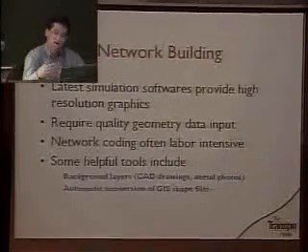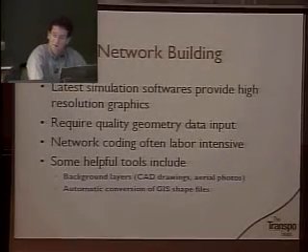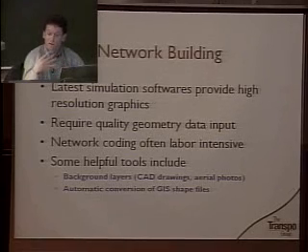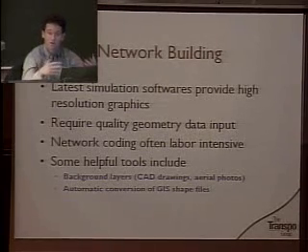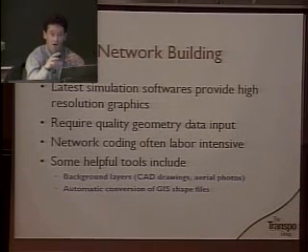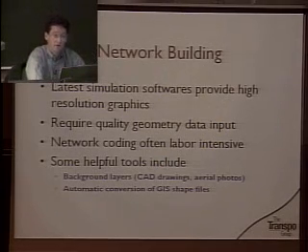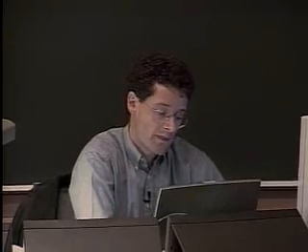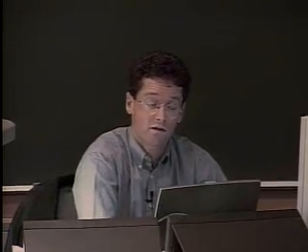And in terms of how we build these models, typically the process is to use either aerial photos or CAD drawings that are actually imported into the traffic simulation software as a background layer, and then you can build your nodes and links on top of this background layer. So that's a very helpful and quite efficient way of building models. Even large models can be built relatively quickly and with a high level of accuracy using these techniques.